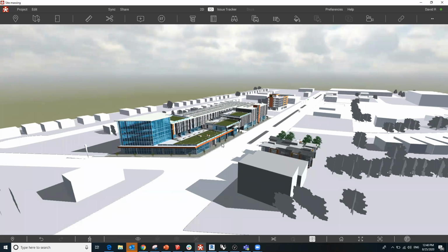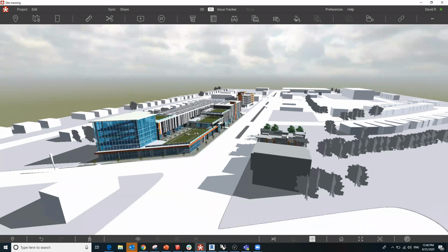Another couple quick things regarding the transform tool. If I want to make some changes in this SketchUp model, Revit model, or Vectorworks model, and I have a transform applied to these positions in Revizto, upon re-exporting those models into Revizto, it'll actually hold and retain those transform points. So I only have to move these models around once. Once they're aligned, any updates I make or any re-exporting I do to Revizto, it will hold those positions.